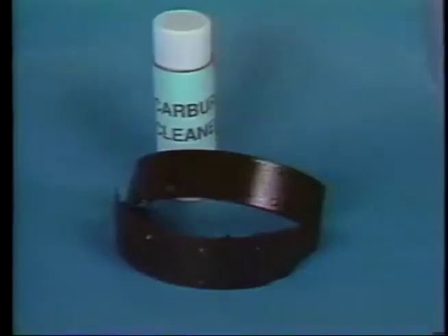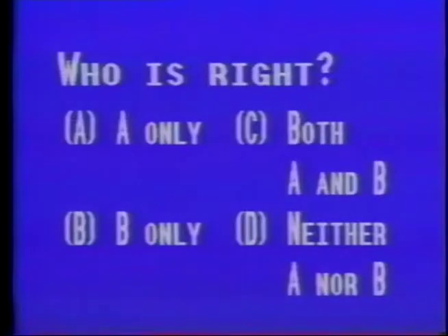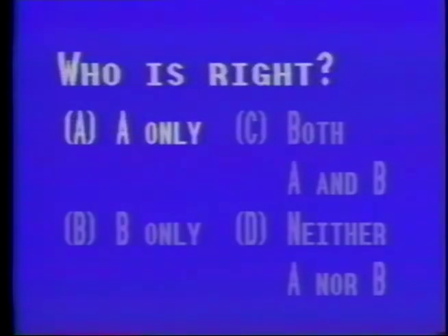Technician A's statement is true regarding a possible leaking axle seal. Technician B's statement is false. You should never attempt to clean oil from brake shoes. The brake shoes should be replaced. Only Technician A's statement is true. So the correct answer is response A.